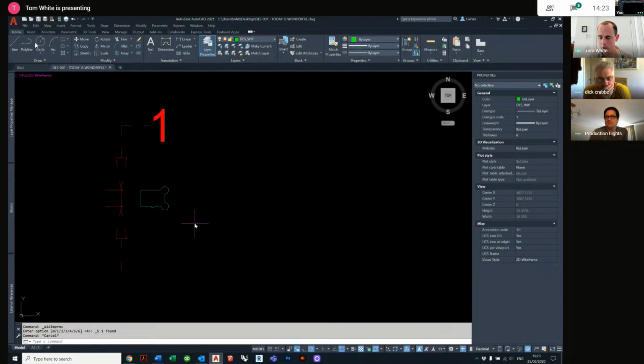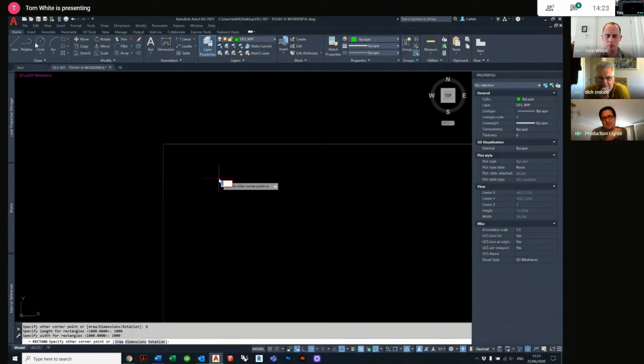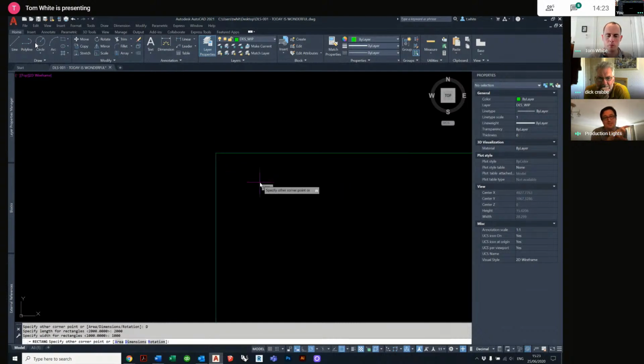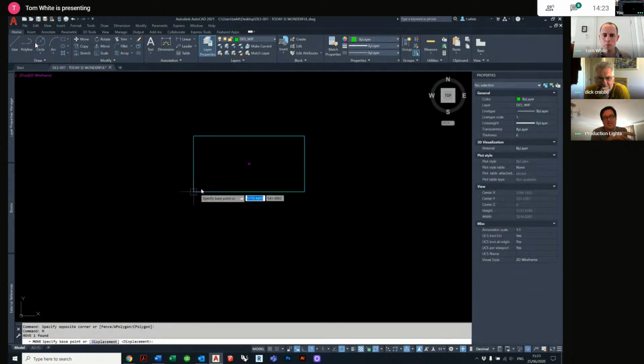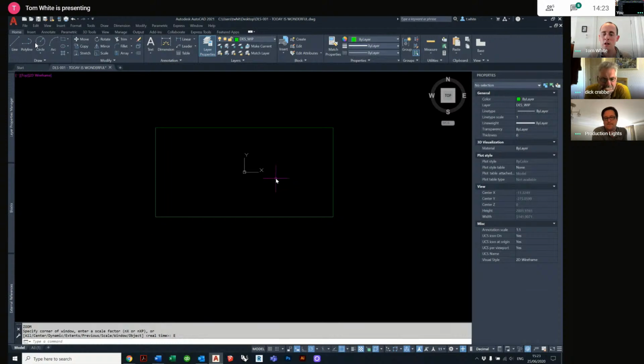That was number 1 of 5 points, which we might not get through, but we talked about stretching and scaling. How often do you use them, Dom? Stretching less so, scaling on a fairly regular basis. It's a command everyone should get their heads around and get comfortable with. I was teaching somebody else this week, and it goes back to the PDF conversations we're having about importing a PDF. Kindly, the hotel PDF had a line on 8 meters, and so we used that as our reference. So we scaled it, used that 8 meters to give us a starting plan, basically, for him to take on a site survey. So that makes sense.